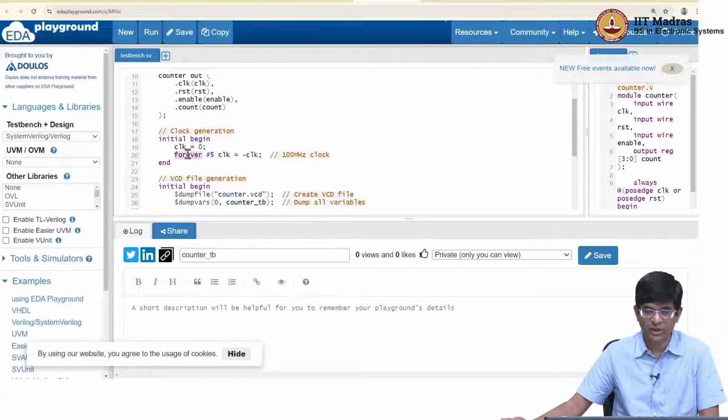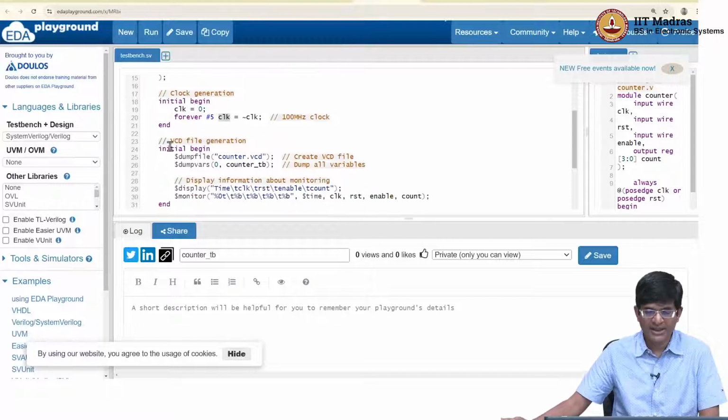So even though there is a forever which very explicitly looks like an infinite loop, right? It turns out that that's precisely what Verilog is very good at modeling. It says, okay, I'm now going to wait over here until time everywhere in my simulation has advanced by 5 time steps, and then I will once again change the value of clock and once more go back to sleep.